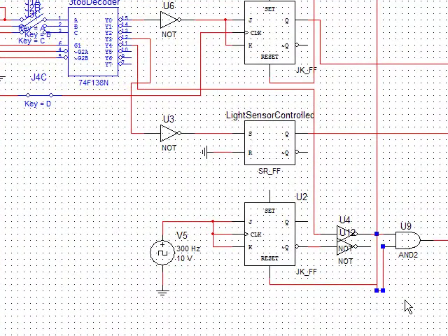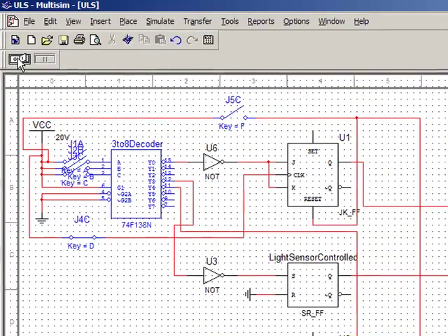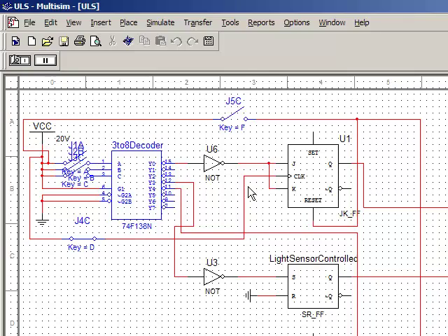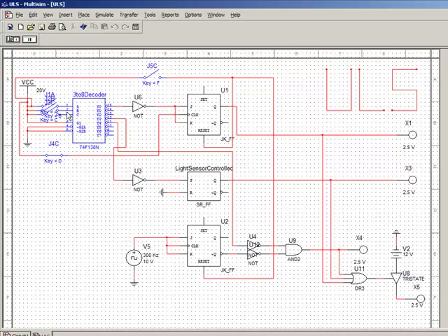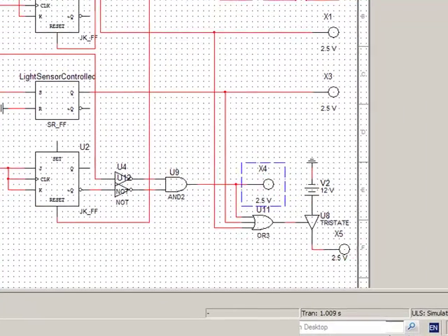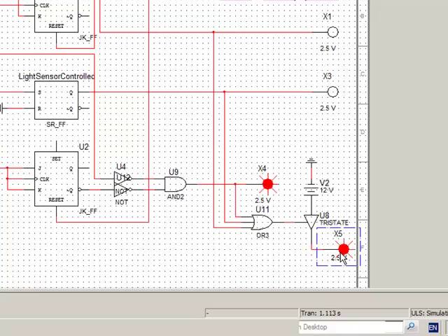And I'm sorry, it was disconnected. And so when we press the simulation button, nothing will appear, because we did not put the binary combination of Y4, which controls the AND gate over here. So when we press the C button on my keyboard, the mode will be activated. Here we are. This is the C, and this is the verification LED, and this is the general LED, which is controlled by the whole circuit.